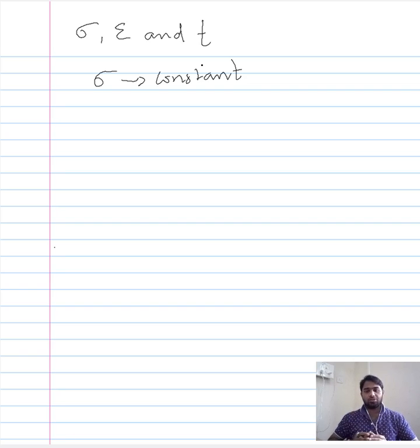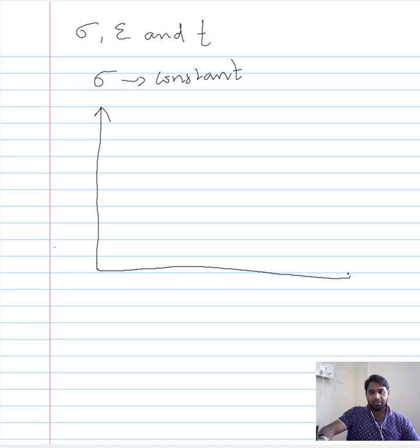Once you have ensured that the stress is constant, it becomes rather consistent for us to represent the creep behavior in two dimensions. To do that, we have to ensure that the stress that we impose on the material is constant all through the test. Then you can represent the response of the material to the given mechanical condition over a period of time that characterizes the creep, wherein you would consider time in the x-axis and the strain, which is not elastic or plastic, it is the creep strain, in the y-axis.